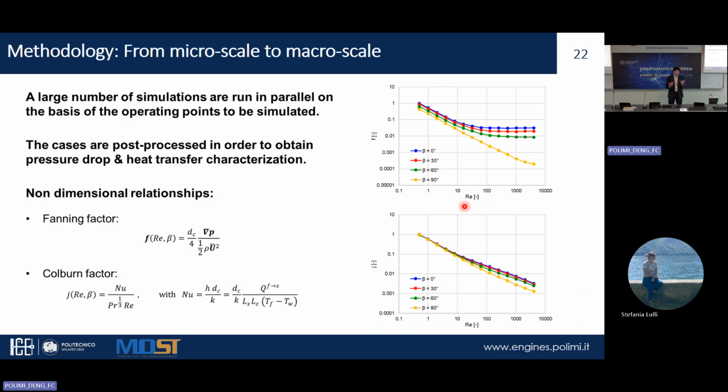Full-scale simulation in which the turbulator, the dimple plate or the strip fins are basically not existent anymore, and there is just a porous media that represents the microscales, the subgrid element. And the resistance of this porous region depends not only on the Reynolds number, but also on the direction of the flow.